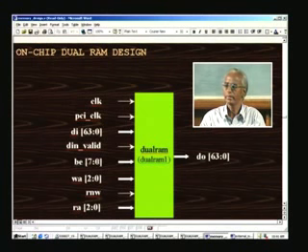either 0 or 1, we can always invert the logic if you find any mistake. I think I have assumed 1 here, maybe 0 is the right thing. So it all calls for just an inversion in the logic later on. So to start with, suppose you make a particular BE bit go high, then only that byte will be written into, and in real practice, being 64 bit, all the 8 will be active simultaneously.